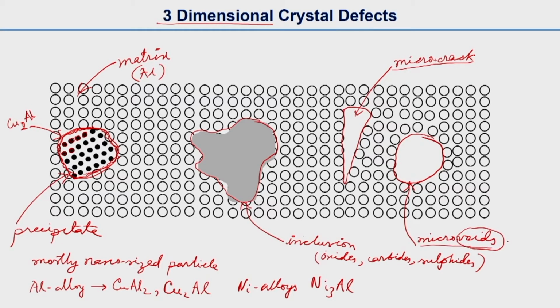Individual voids also grow during plastic deformation, and many voids come together and join each other. First it nucleates, then it grows, and then it comes together, which is called coalescence. That way the ductile material fails. So I will just write that this is related to ductile fracture, that means the voids are responsible for ductile fracture or failure of ductile material.